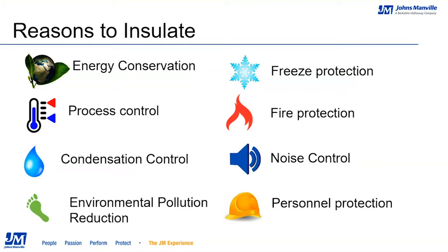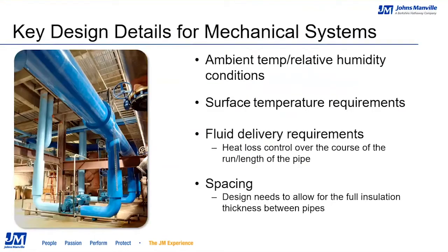Although the reasons listed up to this point deal with thermal issues, insulating can also provide acoustical benefits. Insulation helps to reduce unwanted noise. And finally, mechanical insulation is a key component for personnel protection. Adequate insulation can help bring the temperature of hot surfaces that could severely burn you down to the OSHA guideline maximum surface temperature of 140 degrees Fahrenheit or less.